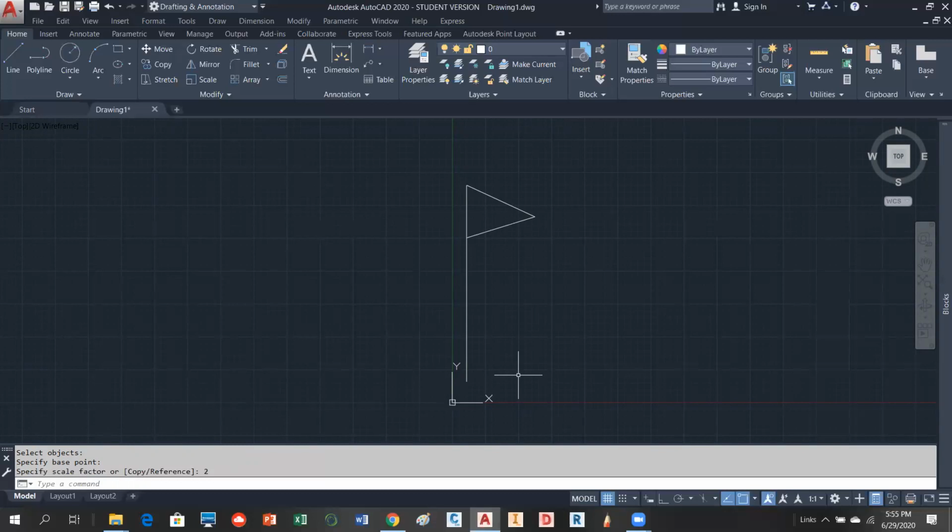So if I have a building that I want to put into, let's say, a boundary, I could insert their building and then scale it down by 12, and it'll perfectly be at the right scale. Or they could take my project and increase it by 12. This is something that we do a lot. The other thing, you could convert, let's say, metric back into imperial by using the factor of a meter to a foot. Everybody kind of get the idea how this would work?